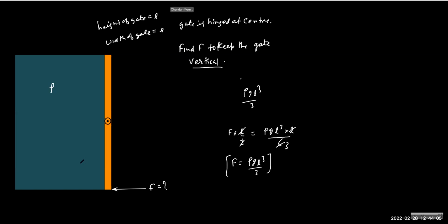Because the center of liquid force will be somewhere here, and I think this is where you went wrong. And you can look at this. How much is this? This is L by 3. So this is how much? L by 6. Correct. So now you understand that you're finding the torque about O, not the bottom, and therefore the answer will not be that. So this part is wrong.